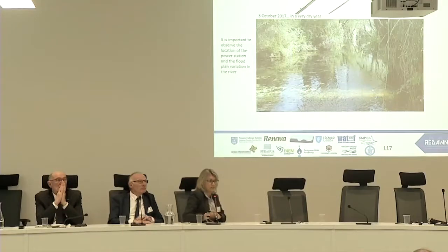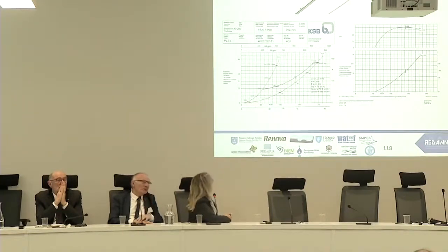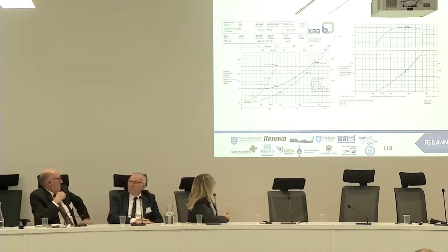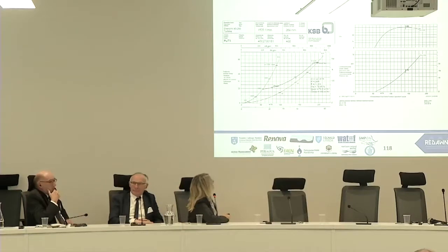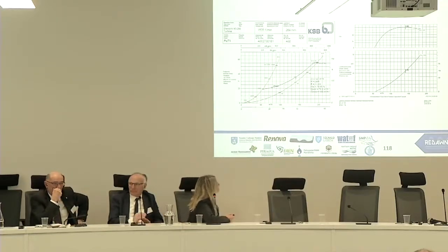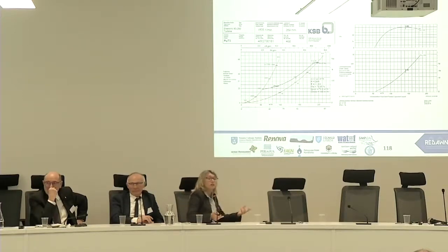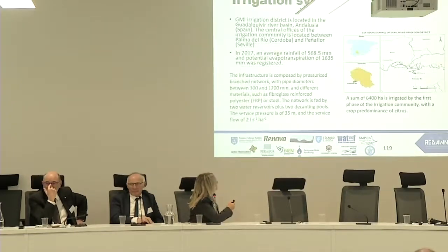Each case is different from the other. Here is a possible pump working as a turbine, considering the minimum and maximum flows, with an efficiency around 80% at the point of best efficiency. Here is an interesting search in terms of the availability of types of energy converters to be used in any type of pilot station.